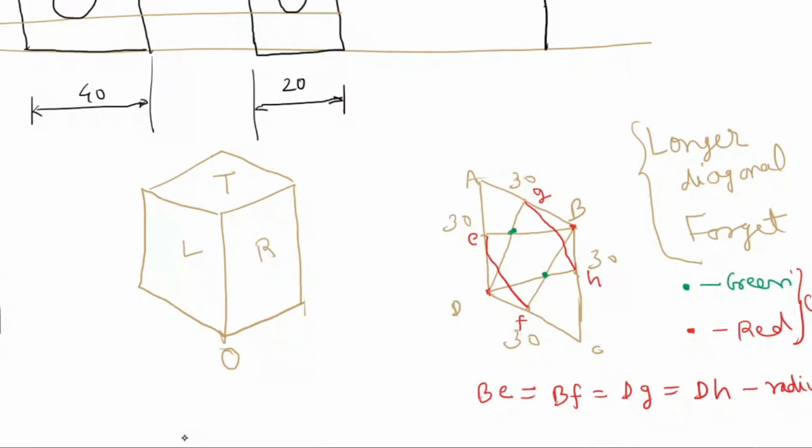Okay, no doubt. Now we have to draw arc with center as these green color dots. You can see these two green color dots. Now the radius will be, you can understand now, this point to G equal to this point to E. These two radius are equal, and these two radius are also equal to this point to F and this point to H. So I will again draw arc. It will go like this, and this will come like this, and we got an ellipse now.